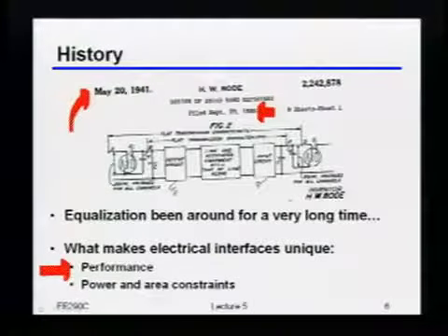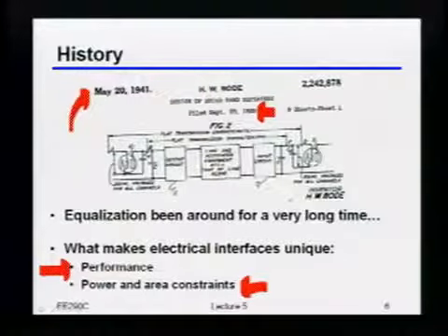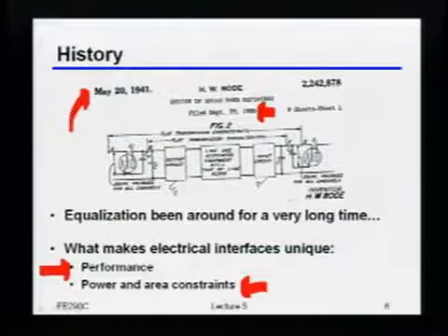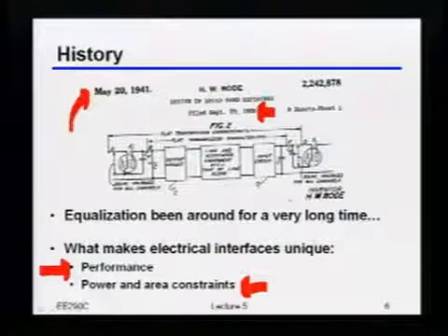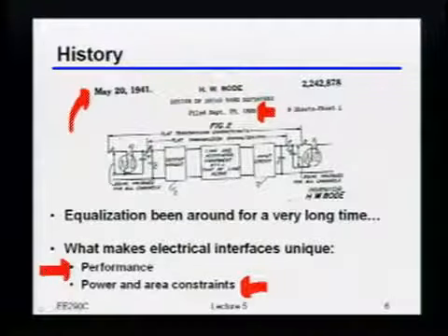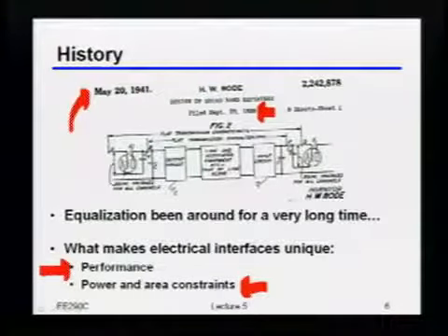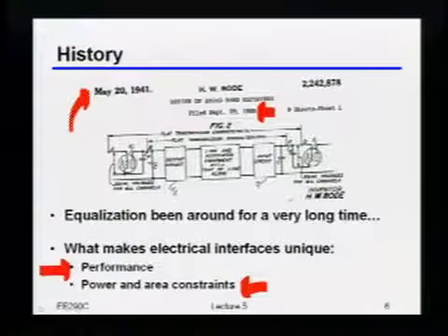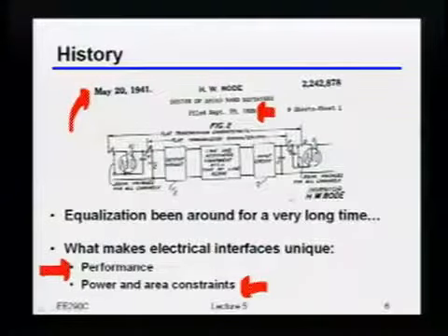The other thing is that not only do you have to achieve that very high throughput, but you have to do it in very, very tight power and area constraints. So this is saying something like, I want that 20 gigabits per second, but I want it in the size of a couple of pads and in like 10 or 20 milliwatts, right? So that very tightly constrains what techniques you can really apply, or really it forces you to be creative in terms of how you build things, because you can't just attack it brute force and meet the constraints that you're interested in.